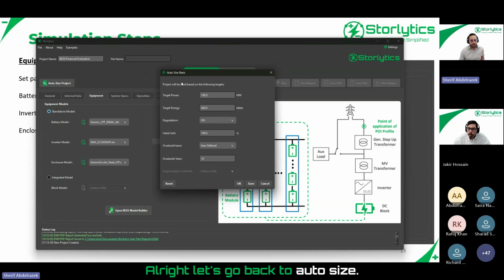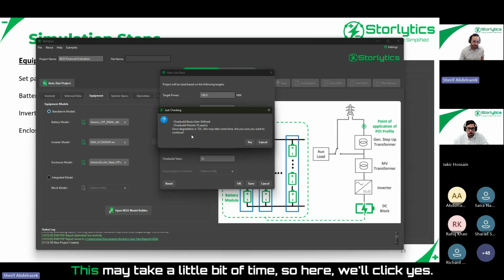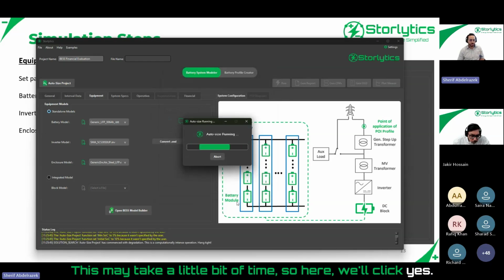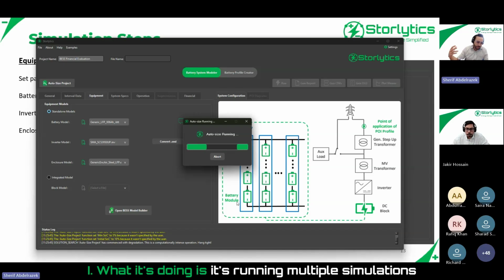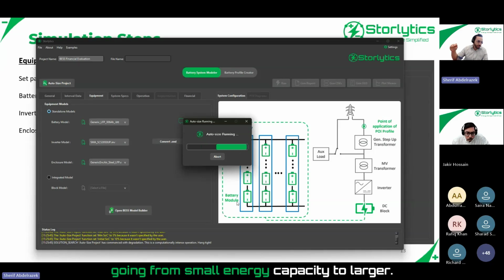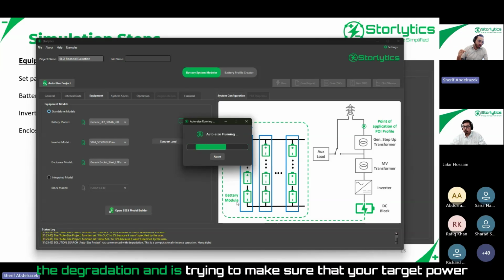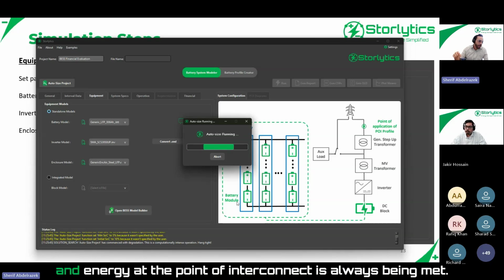Okay, all right, let's go back to auto size. So we went over these items here. We can then click OK. Then it'll tell us, all right, are you sure you want to auto size with degradation? This may take a little bit of time. So here we'll click yes. And what it's doing is running multiple simulations on the back end, trying out different project sizing, going from small energy capacity to larger. And every time it does that, it simulates the project and finds the degradation, and is trying to make sure that your target power and energy at the point of interconnect is always being met.